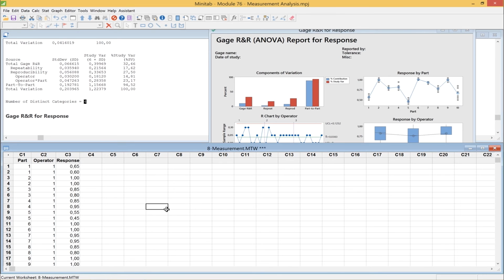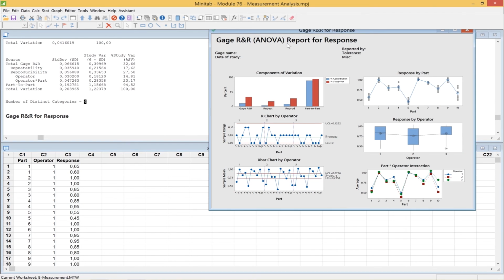Or is it in the one-way ANOVA, where we see there's variation by process step, and that's where we would identify there is a particular measurement problem in one of those steps as a potential source of the variation we're observing. And again, we would come back to the gauge R&R, this one-way ANOVA, to understand what's actually happening at that particular step for that particular measurement. So this is a reminder. This gauge R&R, yes, it's important to do at the end, but it's also important to make sure that we maintain control of the measurement system so unwanted variation due to measurement error doesn't creep into our daily management of the process.